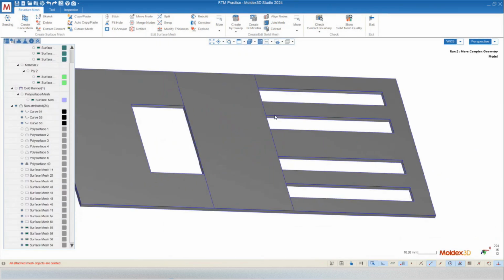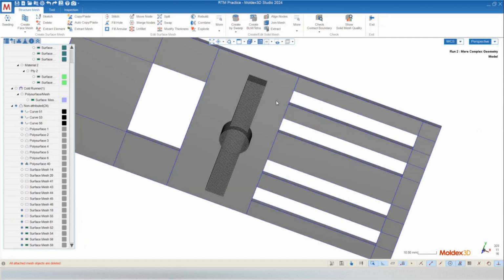I think all of the node seating on this side should be perfectly fine. The node seating on this side and this side aren't necessarily that crucial, and the reason for that is because we're going to be creating a triangular mesh for this surface, just because we have to match that mesh ultimately to the copy that we did.